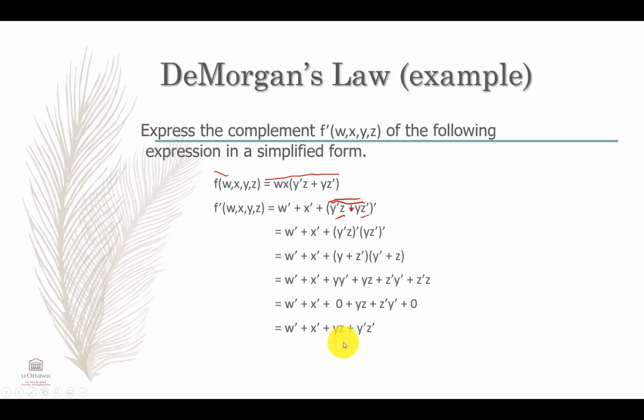So this reminds you of what, guys? Basically this should remind you of an exclusive NOR. So this can be further rewritten as y prime plus x prime plus y exclusive NOR, sorry, with z. Okay.